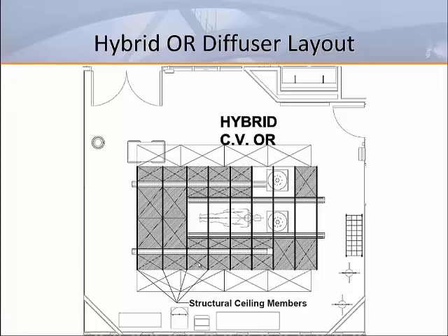Use of custom size diffusers minimized the non-diffuser space within the array and also helped to minimize the overall array size. The resulting diffuser area was 205 square feet. In order to maintain the minimum airflow rate per square foot of 25 CFM per square foot, the total room supply flow rate must be 5,125 CFM.